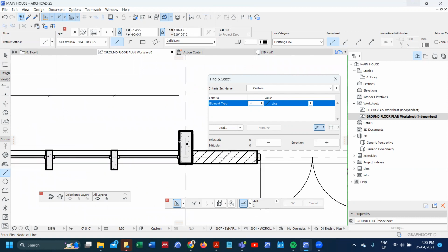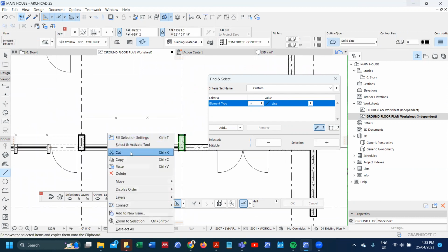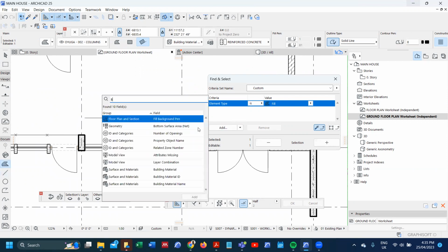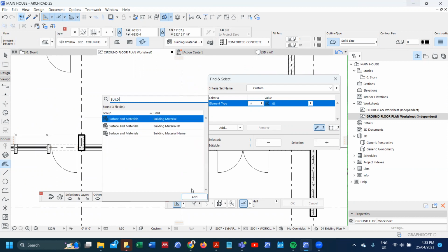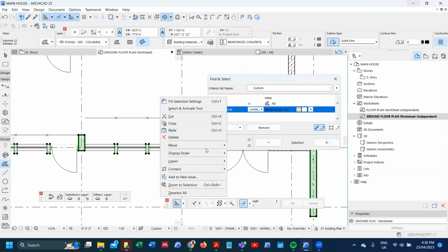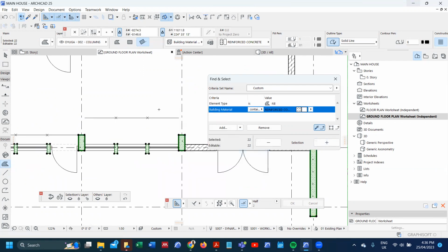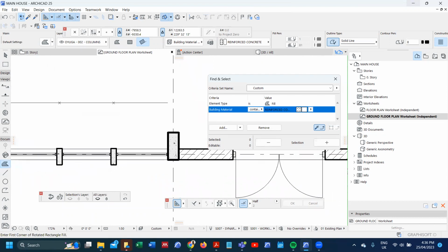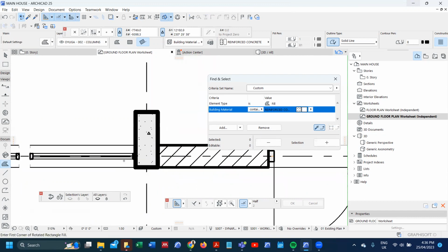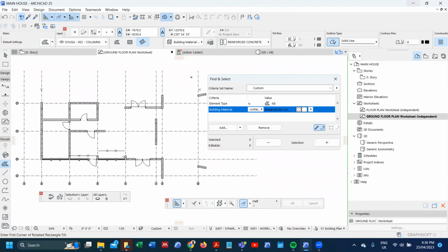We have a display priority issue there. So as a rule of thumb, we can select all our columns and push them to the top in terms of the display on them. Okay, that resolves that issue that you are seeing there. Let's undo and see now by correcting that, that issue is resolved. Okay, so as you can see, it's easy to place your windows, especially if you understand your work so well.